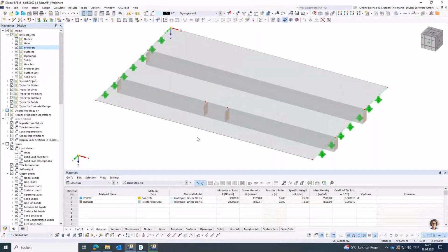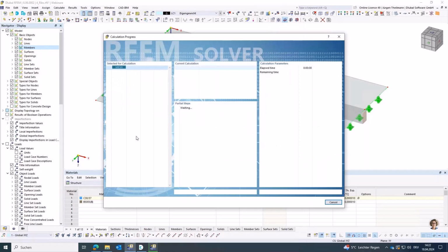configuration, and now I can go here to these nodes, since I have identified them as causing the problem with this polyline. I simply delete them. So now you see it's still one member that goes from node 5 to node 8, but there are no intermittent nodes which interfere with my rib type member. So this is also another possibility to generate the mesh for this model.